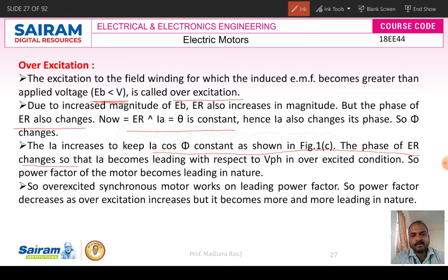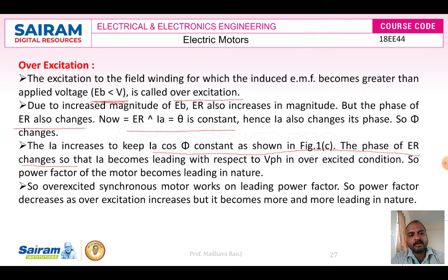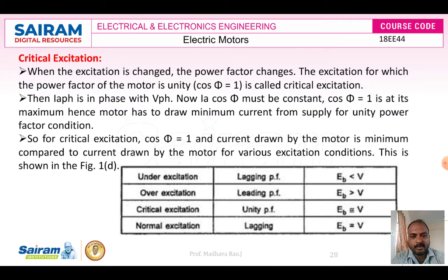Okay. So, now we will see critical excitation. In critical excitation, both induced EMF and supply voltage will be almost equal. So, when the excitation changes, power factor changes.